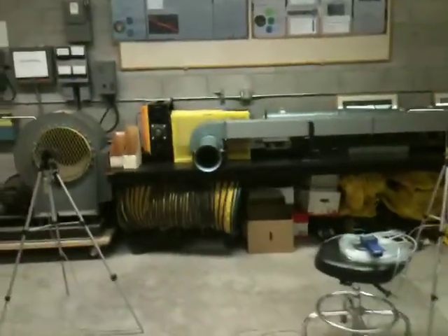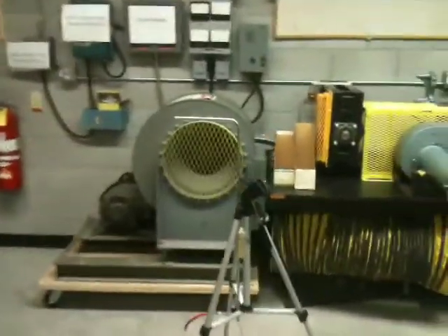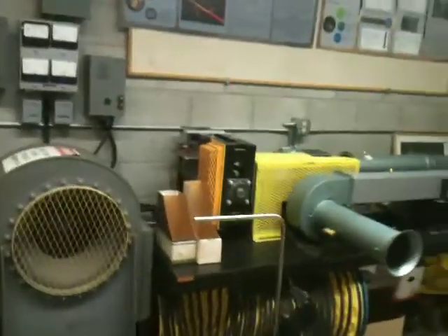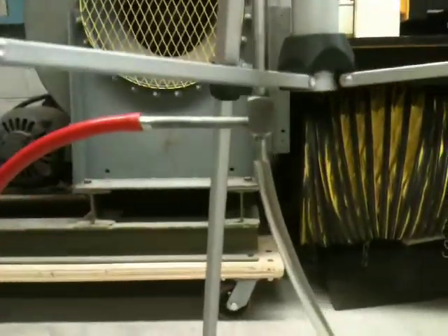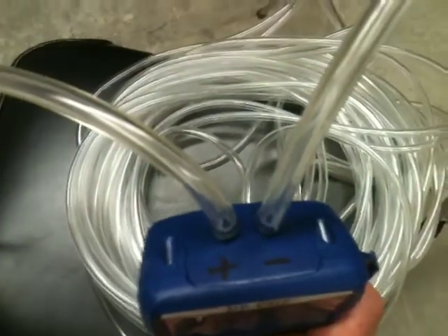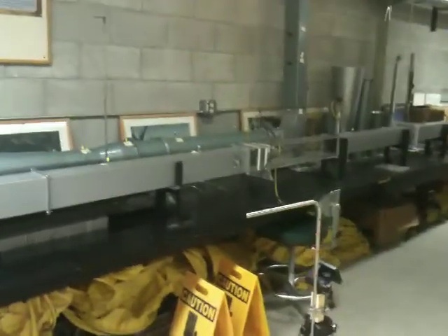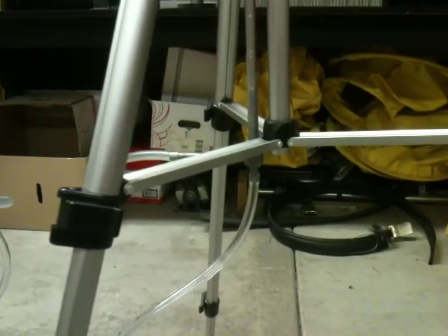All right, here we are in the vent lab. We have two tripods. These are set up in the manner that we would have them set up. So this would be the upstream pitot tube, and then connected to the total pressure tap on this is a single line, which then goes to the manometer and is connected to the positive pressure tap on the manometer. And then conversely, this would be the downstream pitot tube, and its single tube from the total pressure tap is connected to the negative side of the manometer.